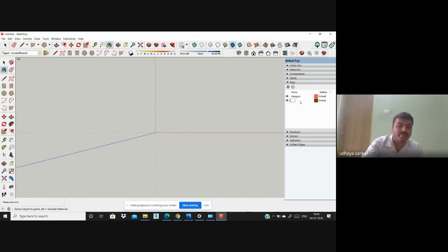Add tag, right? First name is footing, right? Enter. Next name is column. Right. Next name is beam. Right. Next name is slab. Right. Whatever element you want to create, like grade beam or plinth beam, any of them can be directly added. So many can be created, right? I simply created the 4 elements: footing, column, beam, and slab, right? These are the main structural elements to create. Now I go into tags and create the elements like beam, column, footing, slab.